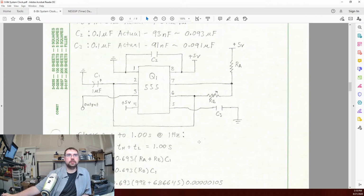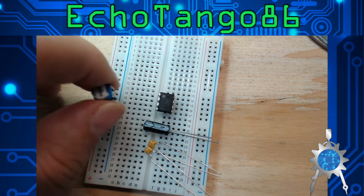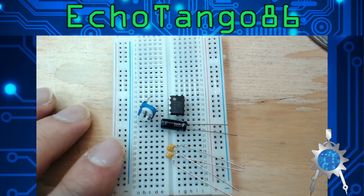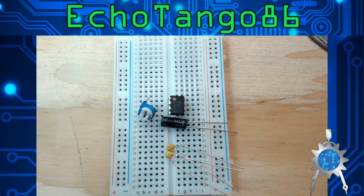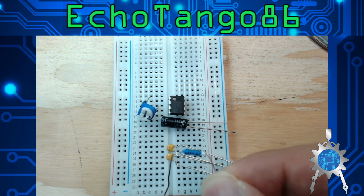So let's go ahead and start building this. Let me show you the potentiometer for the circuit, so we know we have everything we need. So I'm going to use a 1 million ohm variable resistor here. That's that. And then last is our 1K ohm resistor, our RA, that we'll need there.